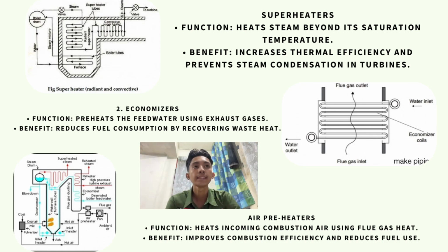Last but not least is air preheaters. The air preheaters' function is to heat incoming combustion air using flue gas heat. The benefit of it is that it improves combustion efficiency and reduces fuel use.